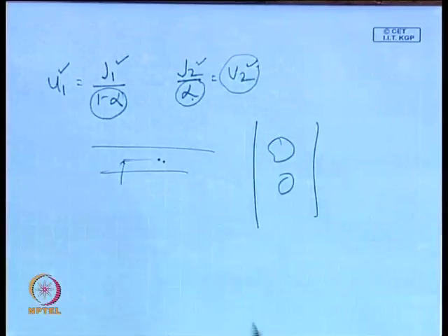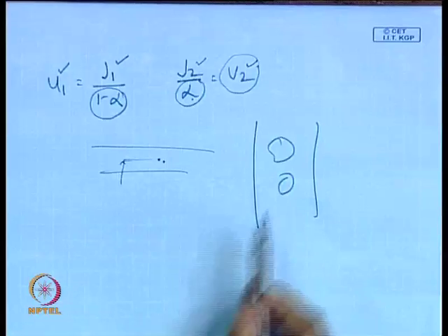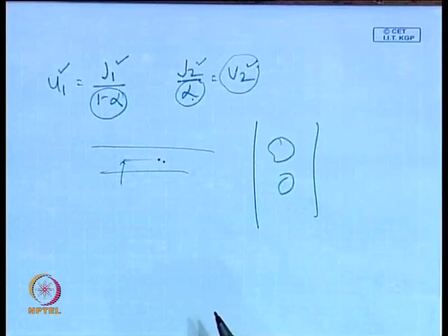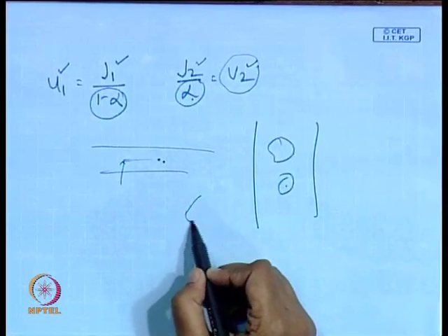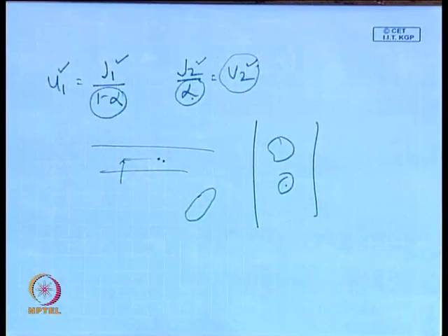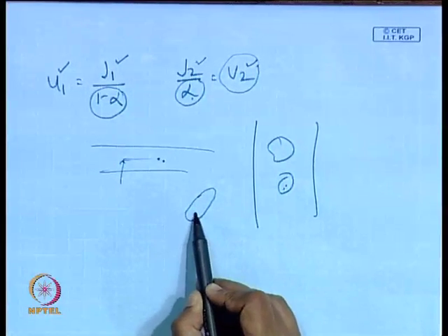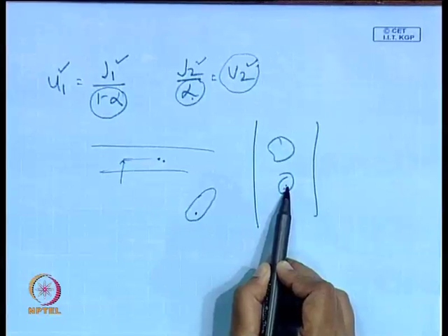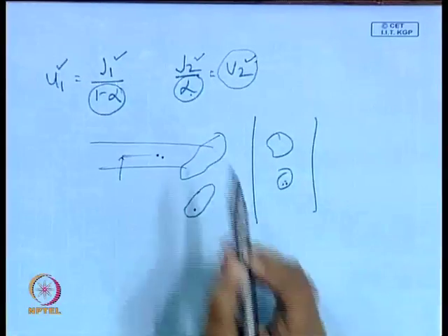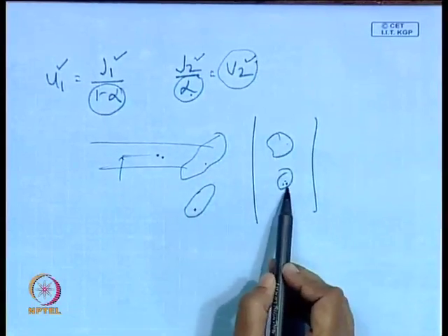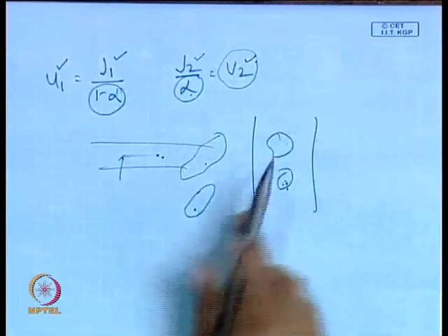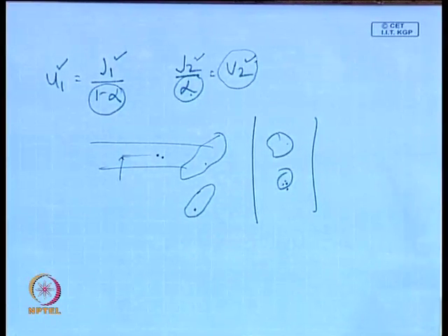Suppose even if it is bubbly flow, okay, with a large number of bubbles. First thing is, when you take the photograph, you will take it from an angle. So, definitely the bubble shape will become deformed in your photograph. So, there has to be a calibration to convert this shape to this shape, and then this shape maybe will become something of this sort. So, for each particular case you need a calibration, and it is very tedious, but it is not that people haven't done it. If they find none of the other methods are suitable, they have to go for it.